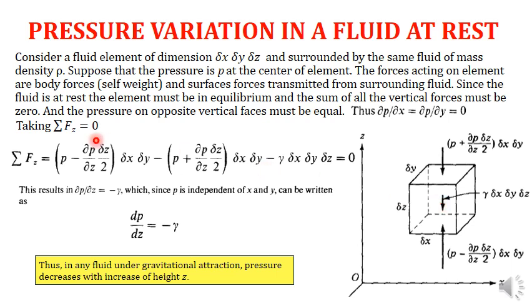So to generate this relationship, the sum of all of the forces along the z direction should be equal to 0. If this is the particular case, then you can write the equations for the forces acting in the y direction. For the surface forces, these are the forces for the top surface and for the bottom surface. In the y direction, two forces are going to be acting on this differential element that we are isolating from the surrounding, from the top surface and from the bottom surface.